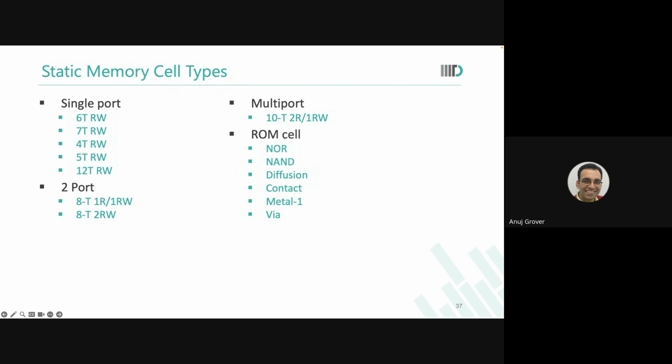So would you say it is impossible to change what is written in a ROM? If you have contact pins at that level, micrometer level, if it's a contact programmable ROM, then no. If it is a VIA programmable ROM, then yes. So maybe from a security perspective, diffusion would be better. We don't know. It depends on how the hacker tries to find out the information there.